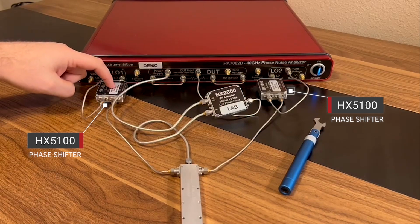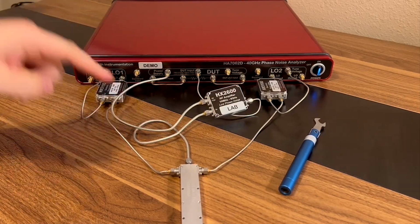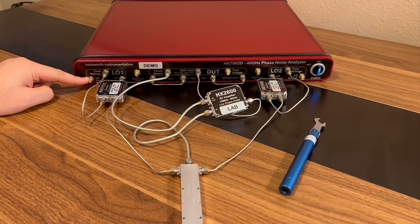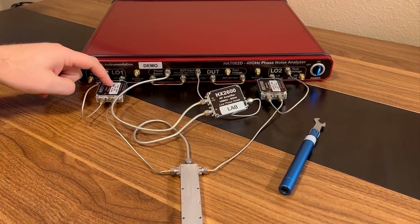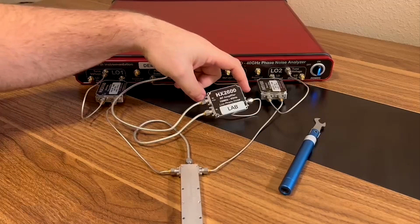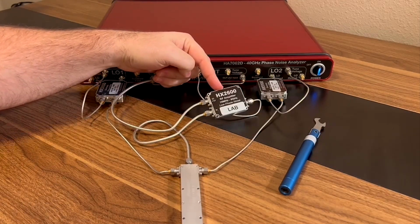That is then phase shifting that signal for cross correlation within the unit. Since we're not using the LO built into the phase noise analyzer, but instead using the signal generator as the LO, we will be able to use cross correlation to remove the signal generator's phase noise, which is coming through this power splitter. And we will only be left with the phase noise that's being generated by our amplifier itself.